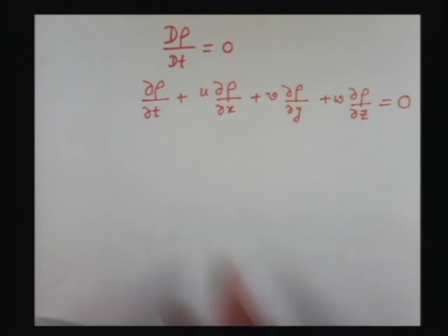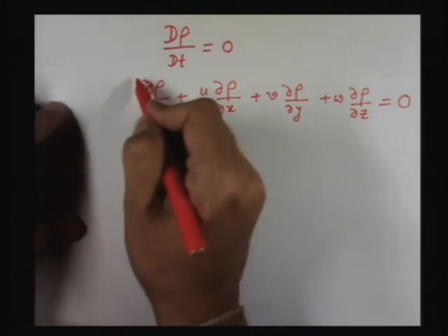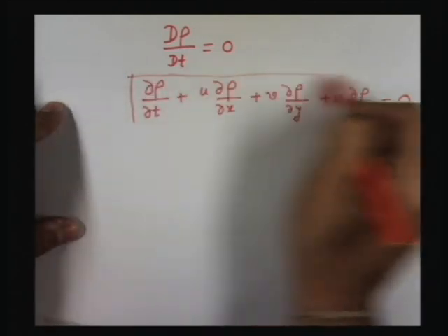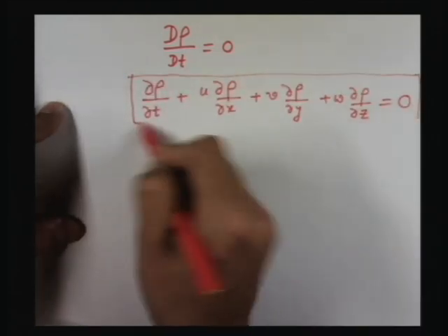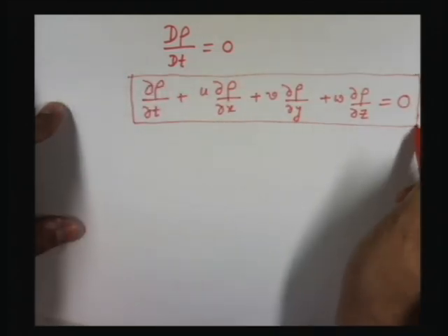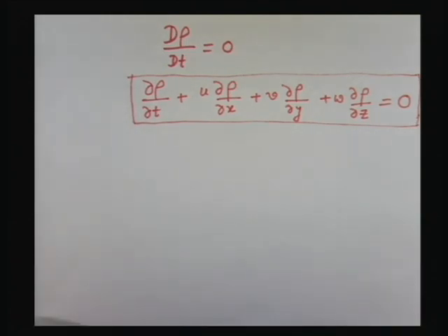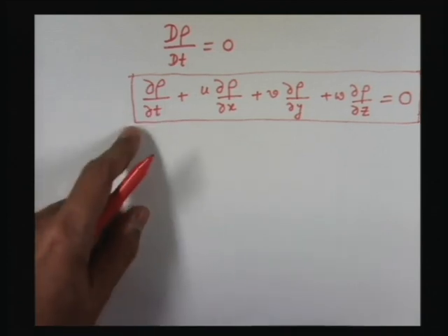So this is a corollary of the condition for incompressibility in the flow. Always remember, the basic definition of incompressible flow is in terms of a kinematic parameter, divergence of the velocity is 0 and nothing else. And this follows from that kinematic constraint.